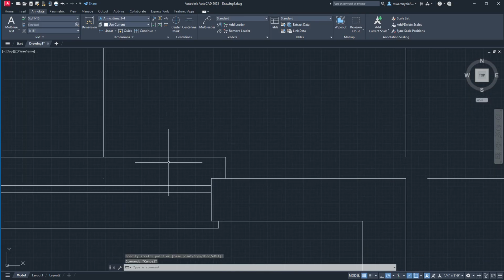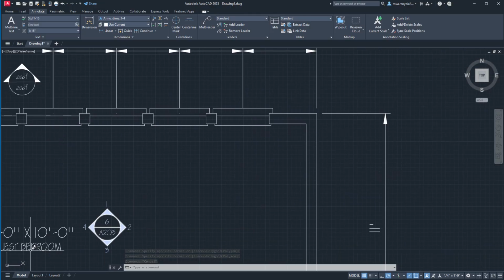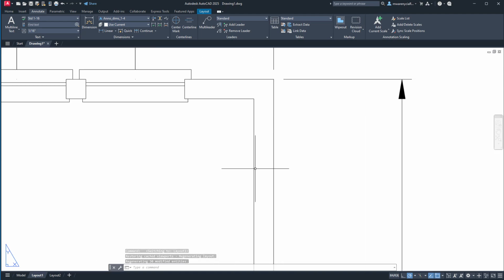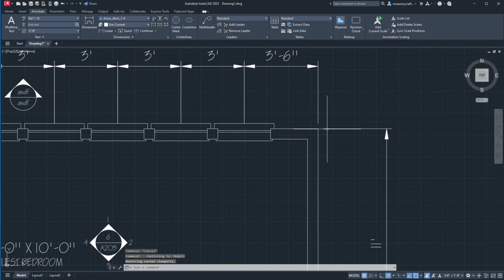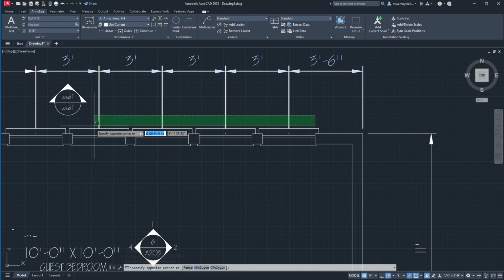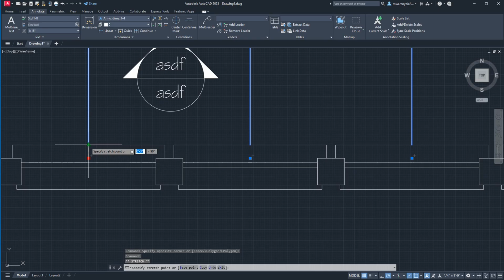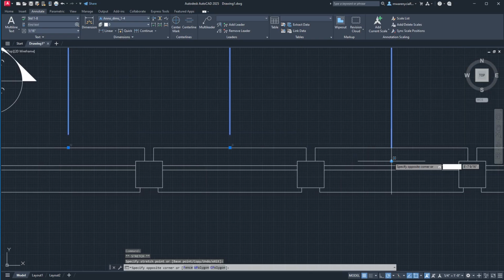Another thing I want to point out is that I have this gap here between the building and the dimension lines themselves. You want to keep that gap. That gap exists there for a reason, because once you go to print this, you're working generally with a lot of black lines, so you wouldn't see that gap. I could probably bring that value down to a 32nd of an inch, and it would be fine. But with these windows along here, once I've done this I would want to come through and bump all of these points up so they're not touching these windows.